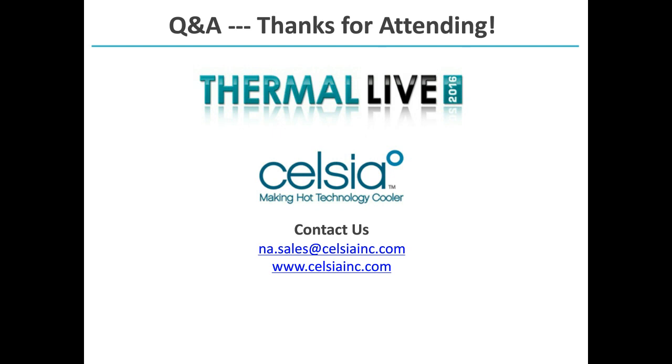The next thing you have to be careful of when choosing a solder is that most of the solders are above the boiling point of the working fluid. For example, let's just use water. When I'm going to solder above 100 degrees C, I start to have a positive internal pressure in the heat pipe or vapor chamber. Now, because the heat pipe's round, it can withstand a positive internal pressure without much distortion.